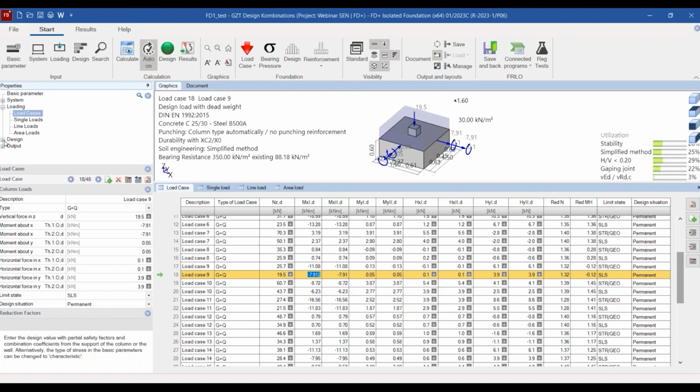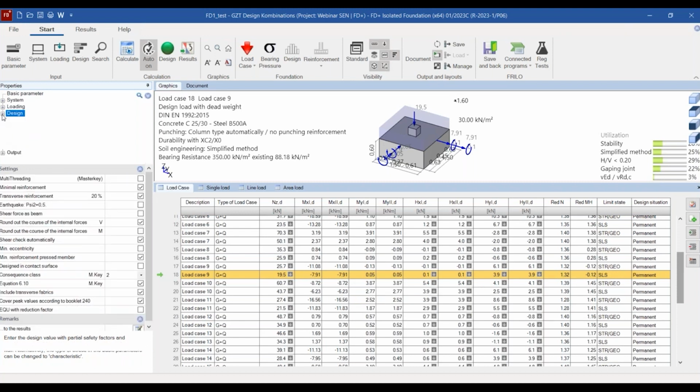You might choose not to do so. So it's a setting you can choose for each check that is done internally, whether you would like to do it regarding those additional forces according to theory of second order or not. So that's the point that can be chosen for each geotechnical check, for example, within the foundation design.